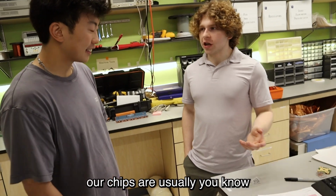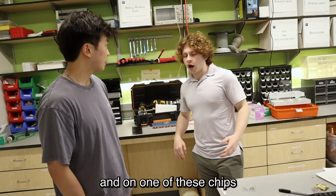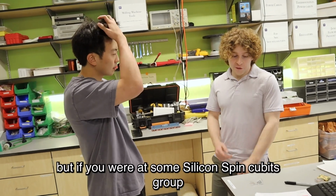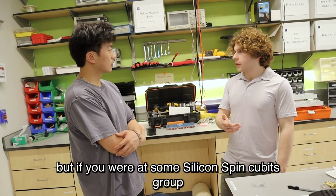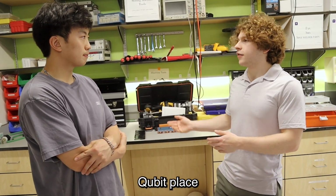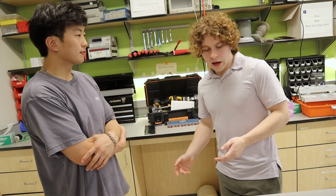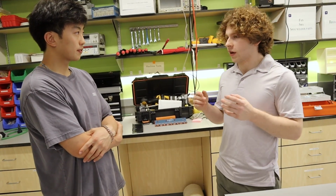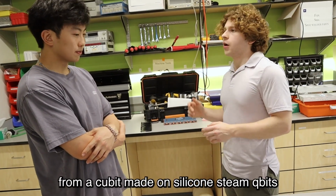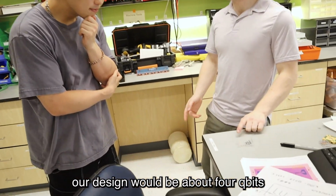But generally our chips are usually about a square centimeter, maybe a little smaller. On one of these chips, you might have 3 to 4 qubits in our case. But if you were at some silicon spin qubits group, that might be a different number. Or if you were at some NV diamond centers qubits place, that would again be a different number. It completely depends on the type of quantum computing architecture that you're using, because the different qubit designs are intrinsically related to that. A qubit made on a superconducting circuit looks completely different from a qubit made on silicon for spin qubits. So for this chip right now, our design would be about 4 qubits.